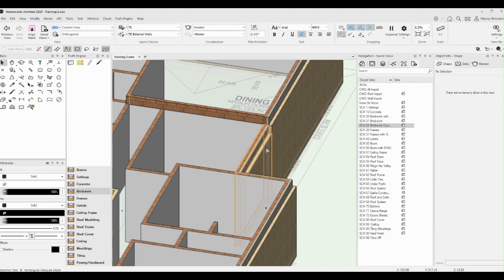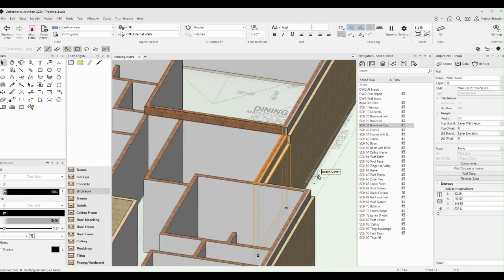So looking at this wall now, we do have 28 course eaves all the way through. So this 2 course face on the outside needs to come back up to 31 courses, but this internal brickwork stays at 28 courses. So we have another tool that forces all the components of the wall to go to the height of the wall, which is 28. So what it will do is we'll move that external leaf face brickwork up 3 courses to 28, or every component in that wall will be moved up to 28 courses.